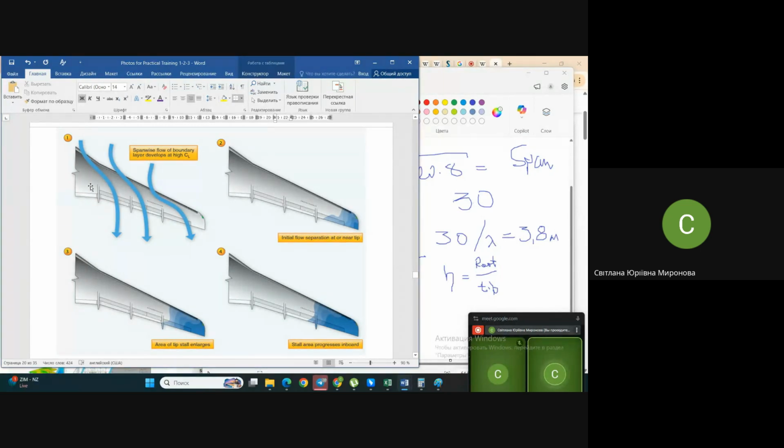The pictures and videos about aerodynamical problems that may appear due to increasing angle of attack or due to improper shape, when we have boundary layer separation from the airfoil. In this case a turbulent zone appears immediately over the wing, and it increases sharply and quickly to the front, and in this case lift just disappears.